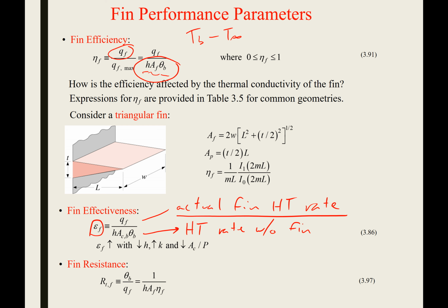So if I'm looking at some big sheet of metal, and I define an area of this metal where I would put a fin, that has limited surface area, right? So it's only going to convect a certain amount based on this fin's footprint. But if I add an actual fin on there, now I've drastically increased the surface area, which means I'm going to transfer a lot more heat.